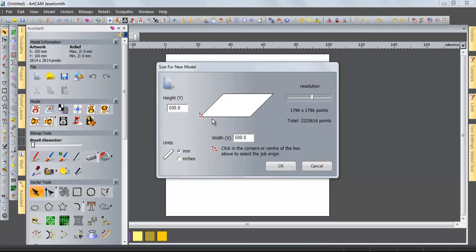When we prepare tool paths, our tool paths will give positive values in X and Y. When we prepare it this way, it will give values Y plus, X plus. When we prepare it this way, it will give values for both X and Y. Even when we set the corner to the left, it will give X plus, Y plus.